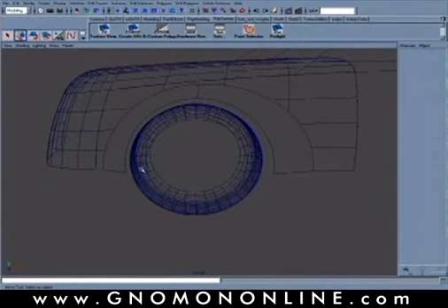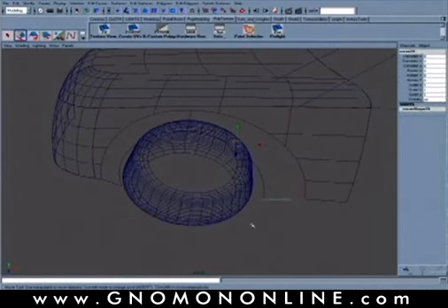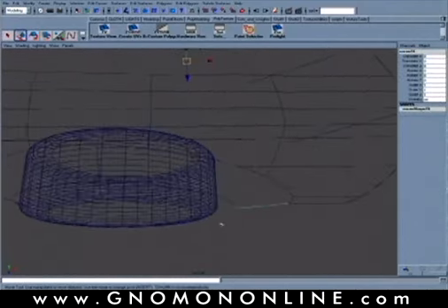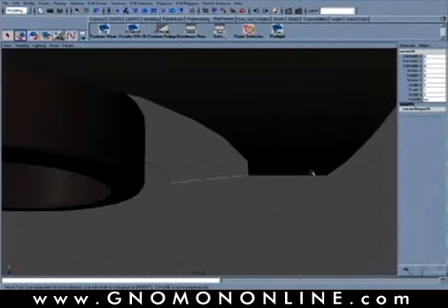Now that we've created the bridging between those, the next thing is to make sure that we have a smoothly integrated surface. If we're going to be using square, we want to build a good ramp for that surface. So on this curve, we want to make sure that it is really smoothly aligned with that other surface here. So this will create a nice smooth tangency.